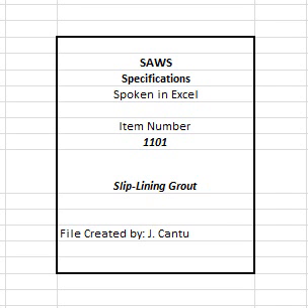C. The contractor shall be required to perform a test on each type of grout and grout system proposed to be used. The test section to be grouted, and the size of the annular space considered for each type of grout system, shall be determined by the inspector. D. The contractor shall engage the services of an approved, nationally accredited, independent testing laboratory to certify that the proposed materials and methods comply with these requirements.